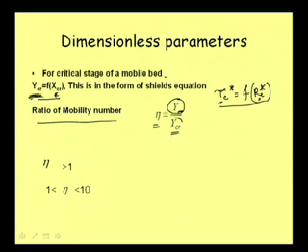And we know the mobility number in the critical condition, which is a function of, say, x critical, that is the r c star. So, we can find a ratio eta, and it is seen that when eta is less than 1, then basically we have not reached the incipient motion condition. No flow will be moving.